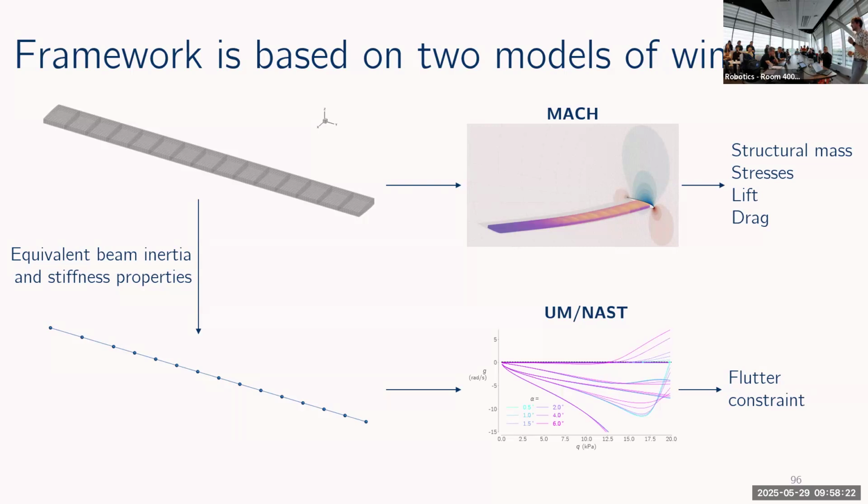Actually, the truss-braced wing, even though it deflects less in flight than we show here because of the truss, some people have actually shown that even at those lower deflection levels, you need to use nonlinear analysis to correctly capture the loads in that truss. But I think what they're focusing on now, instead of the truss-braced wing, is what they call a thin wing, which is really just an even higher aspect ratio wing, where